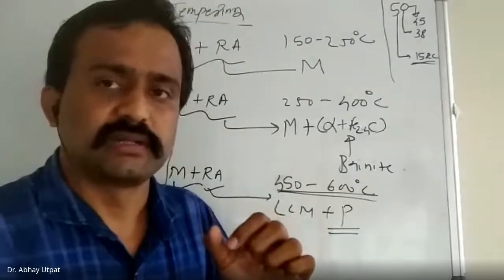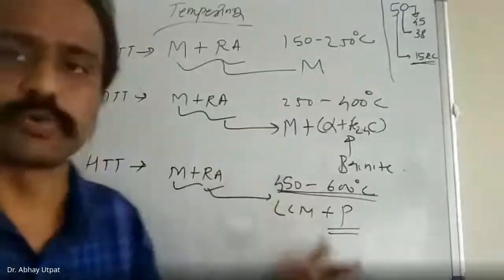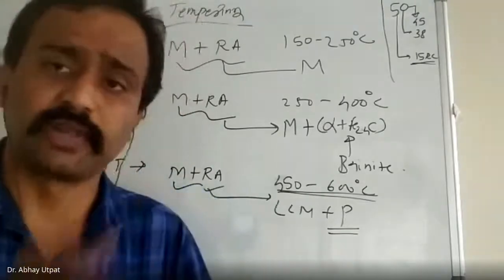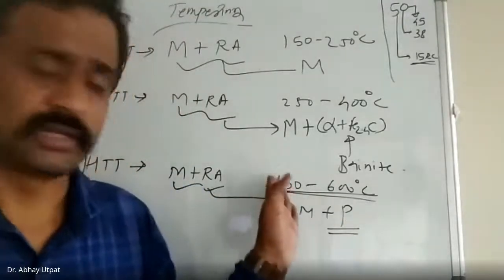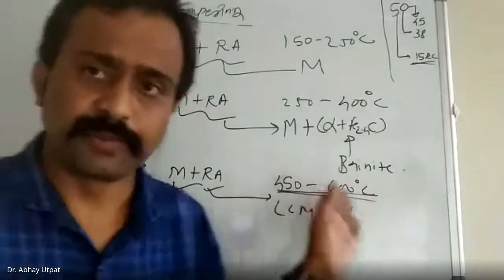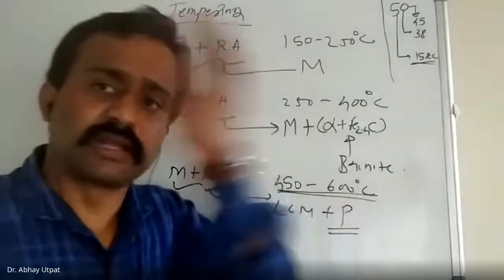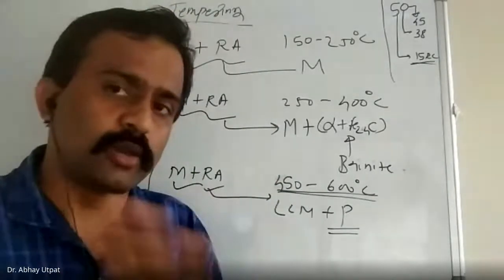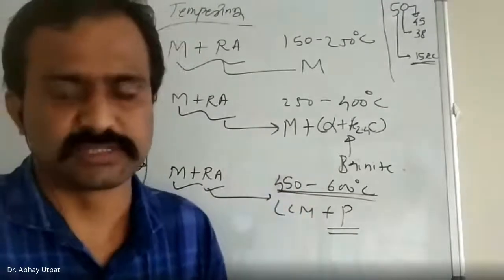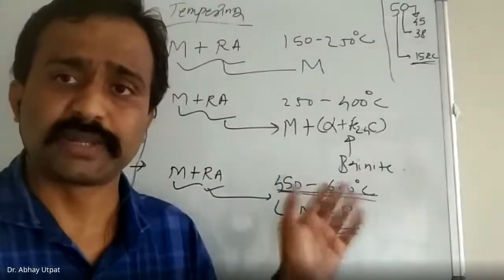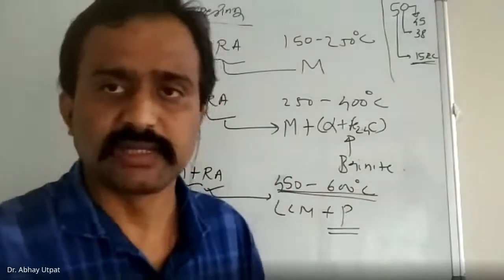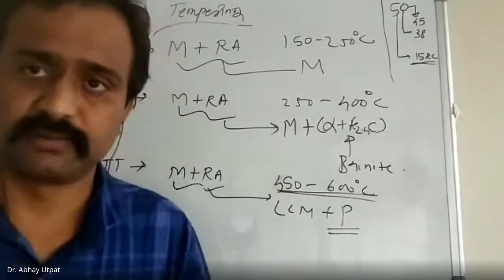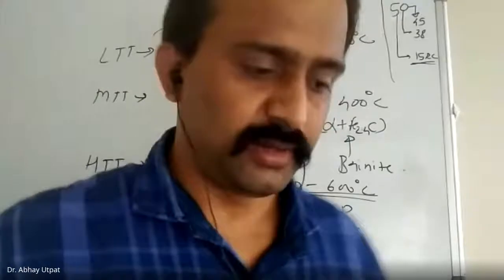Okay. Now, many times what happened? There are certain alloying elements which may disturb this response. These certain alloying elements are usually phosphorus, sulfur, and other elements like manganese. So when you heat these samples in tempering, there is decrease in the toughness and improvement in the brittleness. This is not true for all steels, but for certain types of steels. This is because of the presence of these particular alloying elements, and that concept is called temper embrittlement. Write down the title. Temper embrittlement.